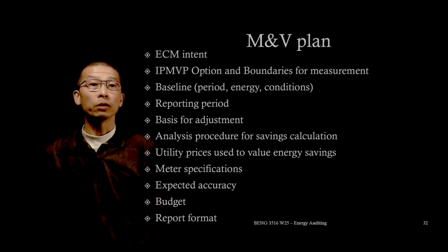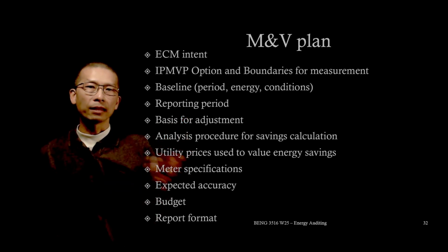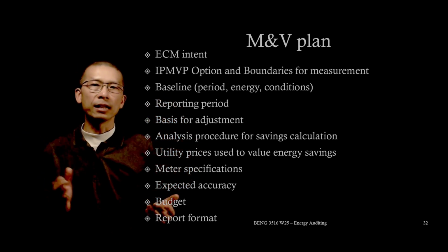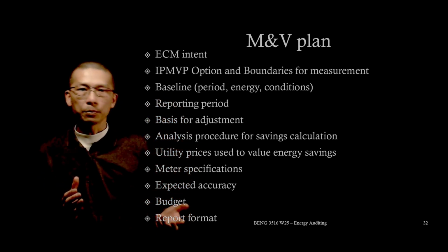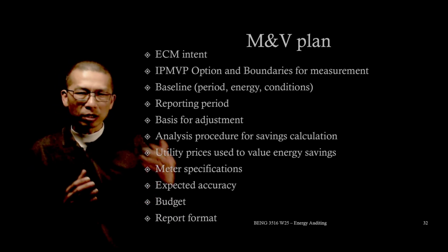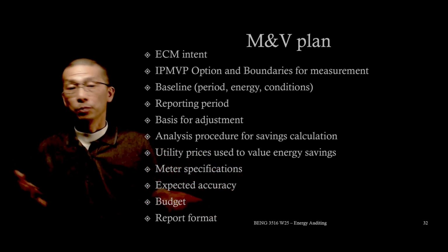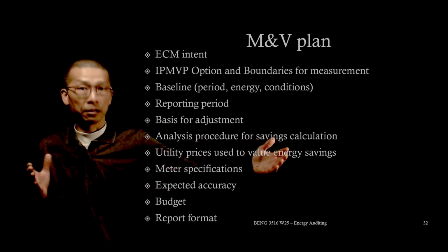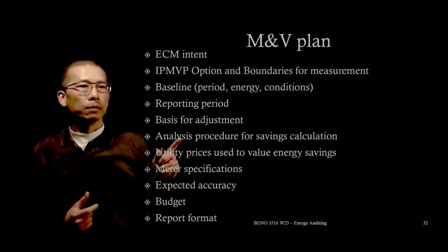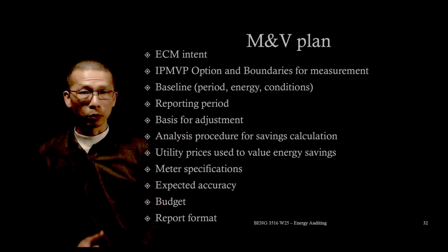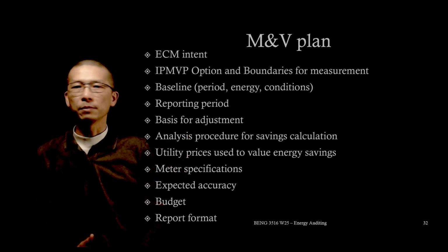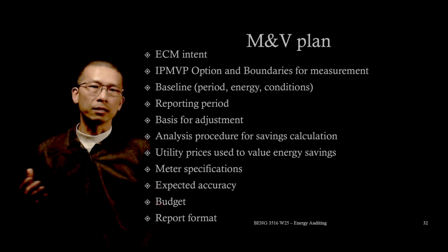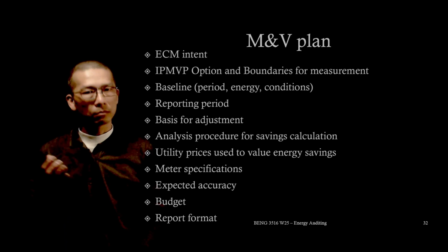Okay, reporting period. Identify the time frame during which post-implementation energy data will be collected. This period should be just long enough to capture the performance. We don't want it to be too short, but we don't want it to be too long either. Yeah. The basis for adjustment, that's a very important one. It describes how adjustments will be made for variations in weather, in production level, things like that.